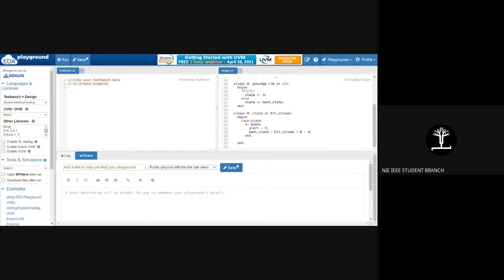So that's basically a bird's-eye view of an application of the CAN protocol, but we are using an FSM to simulate that. And for that, we are taking a small message, that is 110. I'll append it with the start bit, or you can just say the whole thing is 1110. You can take any sequence you want, and all we are doing is detecting this sequence using Verilog. That's what we've done until now.